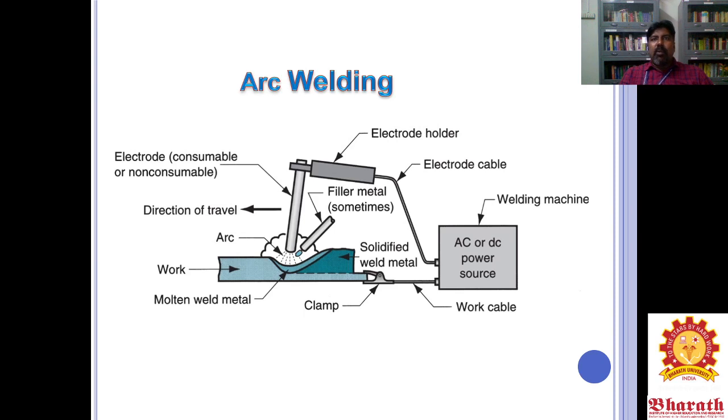The molten metal is forced out of the pool by the electric arc, and hence a small depression may be formed on the parent metal when the molten metal is piled up. This is known as the arc crater, right? And the distance between the tip of the electrode and the bottom of the crater is called the arc length.